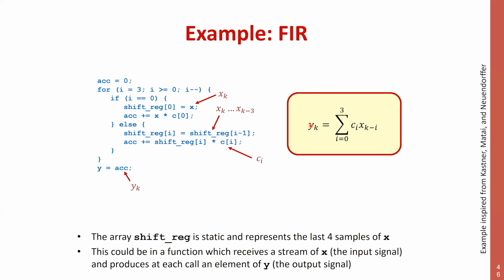It's used in a lot of signal processing situations to do every sort of high pass, low pass filtering, and so on and so forth, depending on the shape of the kernel of the constant C. This is a super simple, ridiculously simple version with only 4 taps for constants. So it's very short. Typical real applications these days, I think, have 128 taps or something like this.